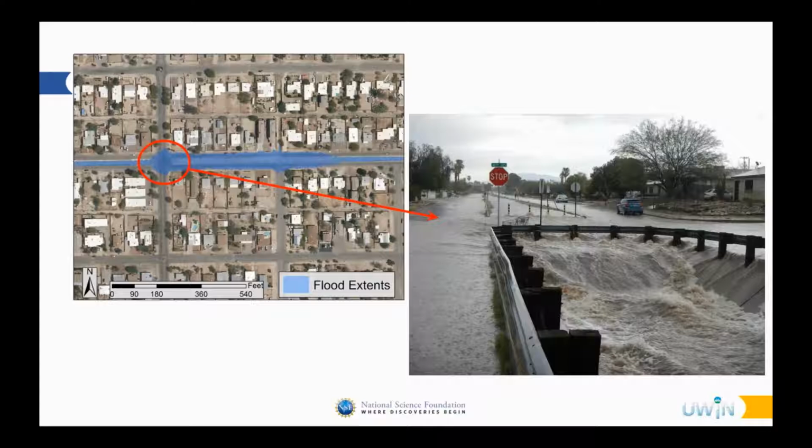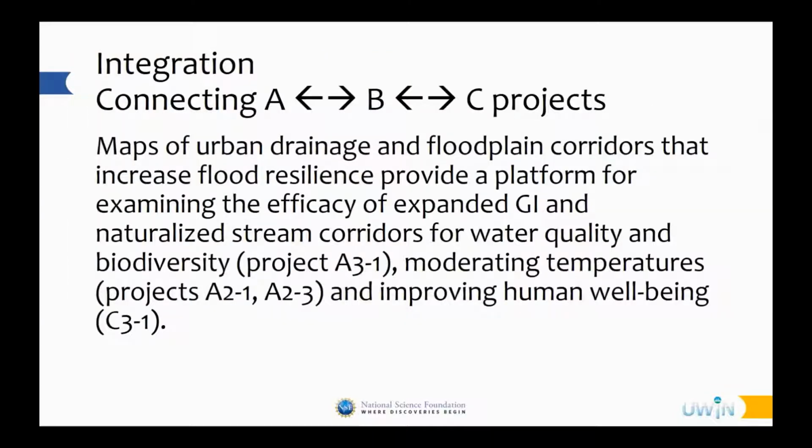So that's some of the current work where we're bringing these components together, and I think Yoga's working with Jim to get some of the stochastic storm transposition and radar rainfall fields to bring into the hydrologic model, and then we'll be able to further feed those into the HEC-RAS models and bring this into a Monte Carlo framework and develop a probabilistic floodplain map for this particular location. And so that should be coming soon.